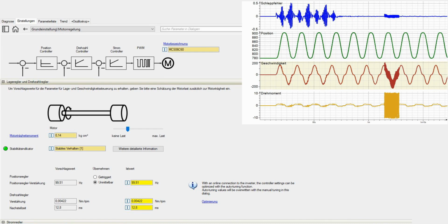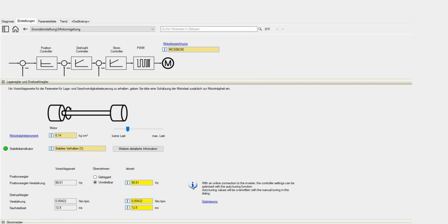It can be seen that the following error quickly drops significantly when the load is increased and only noticeably increases again during instability. Similar noise can also be seen in the speed and especially in the torque during instability. With final controller setting, this example results in a maximum following error of about 0.01. Alternatively to this procedure, the auto-tuning tool can be used to perform an automated and optimized controller optimization.